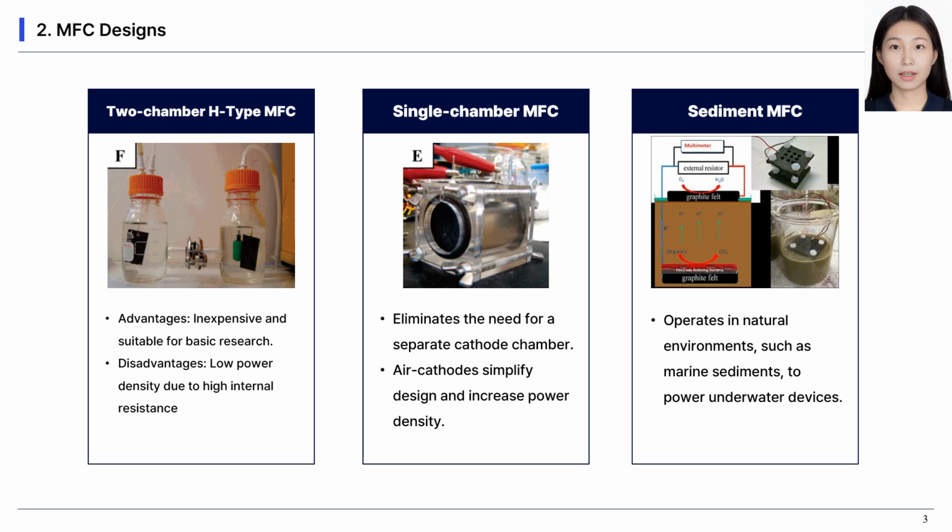Lastly, there is the sediment MFC. This design leverages natural environments, such as marine sediments, to generate electricity. The anode is placed in organic-rich sediment, while the cathode is positioned in the overlying water. The redox gradient between the sediment and the water drives the generation of power. Sediment MFCs are often used to power low-energy devices, such as sensors, in remote or underwater environments. Each of these designs has its advantages and limitations, and the choice of design often depends on the specific application or research focus.